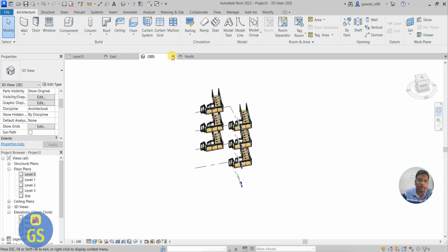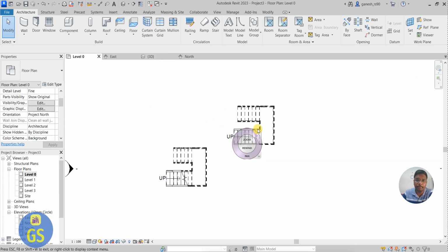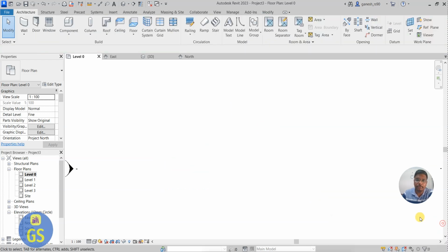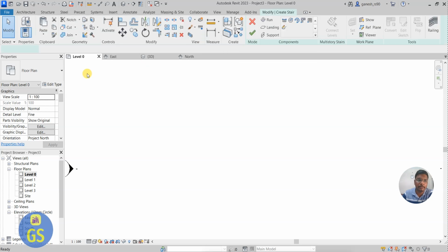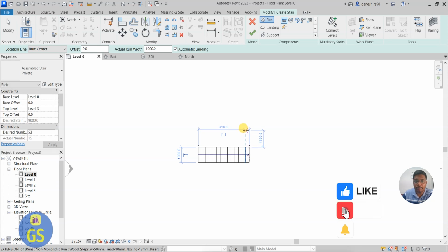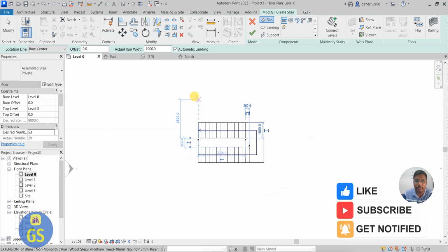In a similar way, we can also do it in an alternative way, copy one part and repeat it in the other staircase. Now see here, now we'll untick all this part. Now go ahead to normal type stairs. Once you select here, you can select the top level, third, and automatically 54 steps are required. So if you calculate automatically from level 0 to level 3, 54 steps are required. So you need to draw the staircase. First you want to draw it fully, so this will be a lengthy part. So 1, then again, then again.